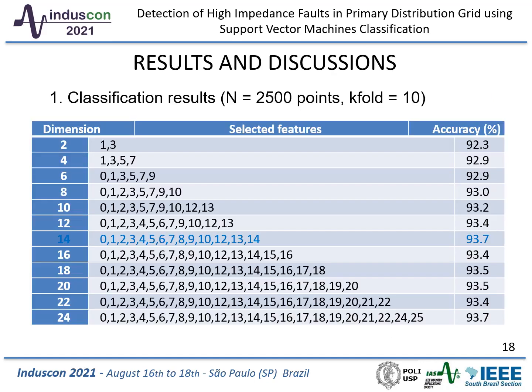To train the classifier, the selected set of features comprising its classification were fed into the Classification Learner toolbox in MATLAB. To analyze the results, STFT was applied on the residual current considering two distinct window lengths: 2,500 points or 3 60 Hz cycles, and 5,000 points or 6 60 Hz cycles. Likewise, the selected feature vector was also varied considering the aforementioned range.